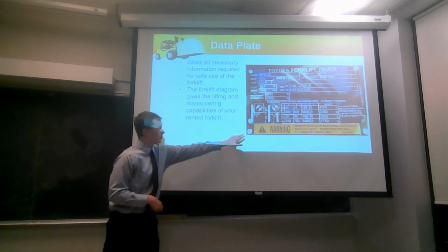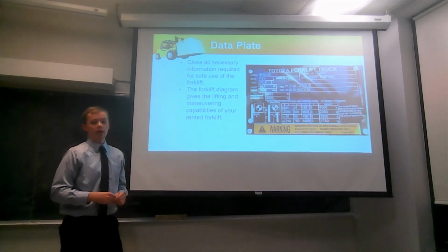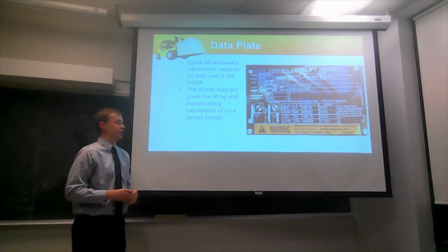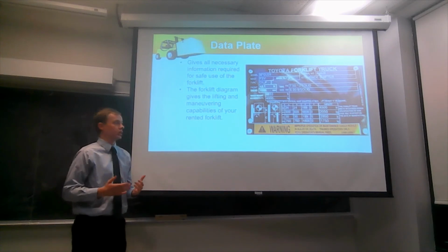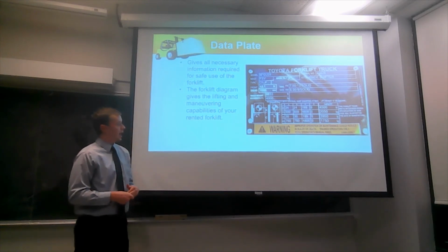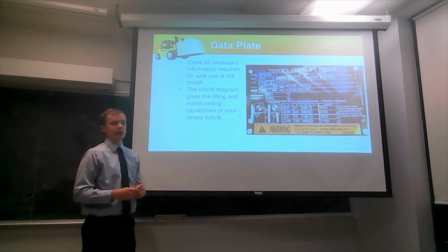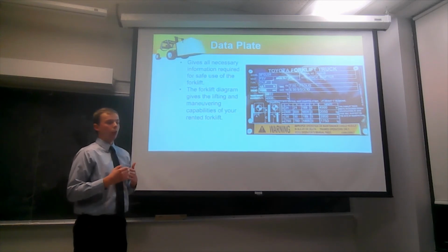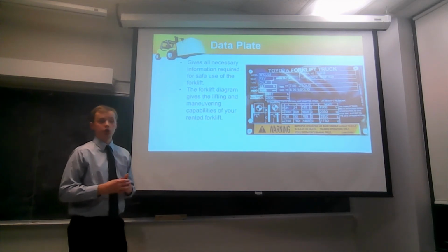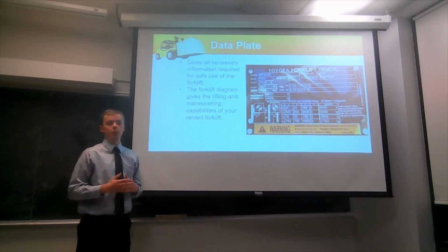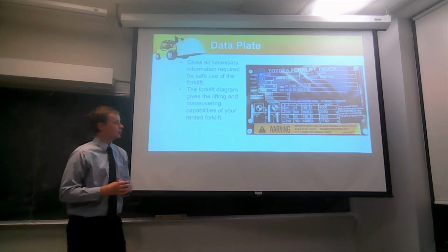And this diagram here at the bottom gives you the information regarding the center point of your load that you're trying to lift. And it gives you recommendations on what size of forks you should use depending on the center point of your forks or of your load.